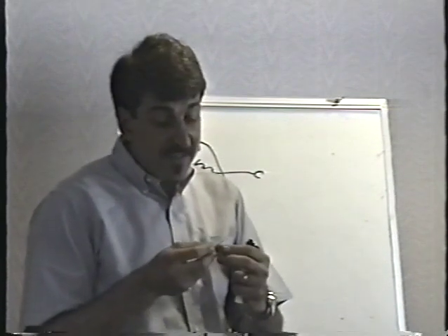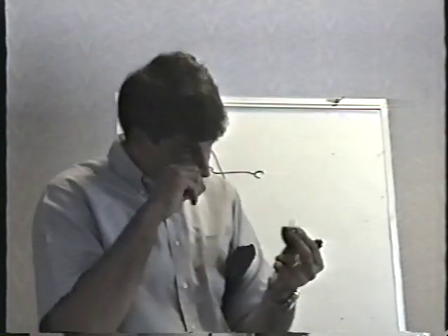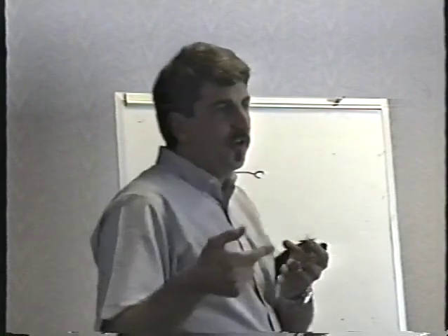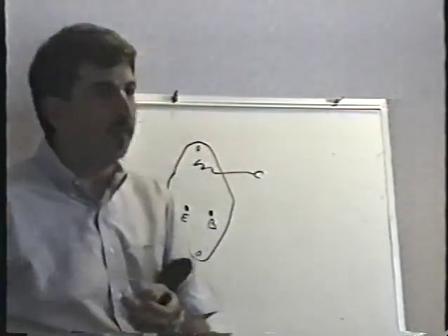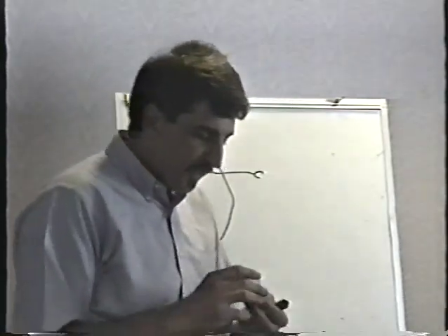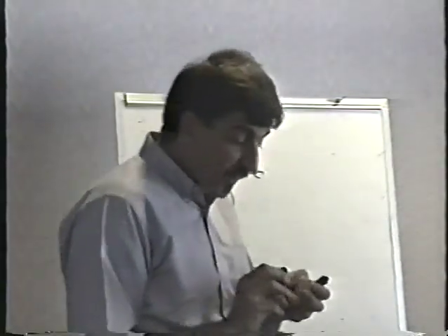When you see it, it doesn't mean that your transistor exploded or anything. That's perfectly normal. People put that stuff on. You're supposed to put new heatsink compound on whenever you change a transistor. I don't do it because I was trying to be very professional for a while, and I carried a little tube of it around in my toolbox till my long nose pliers skewered the tube and got this white crap all over my tools. I'm sure whoever stole my tools still has that white crap all over them because I couldn't get it off. So anyway, be aware of that.